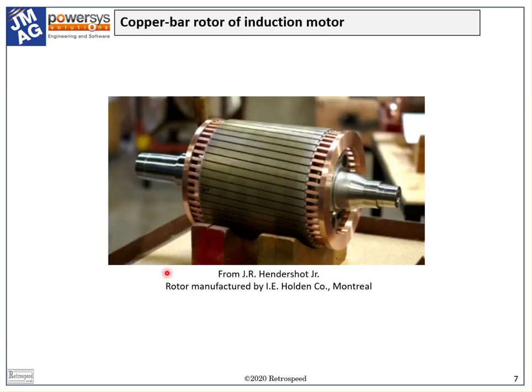Now, we can keep that stator, and instead of a DC salient pole field winding, let's have a cage type induction motor rotor. Again, although this type of rotor has been made for more than 100 years, this is a modern example of a fabricated rotor with end wings welded to the cage bars and designed for operation with an inverter.